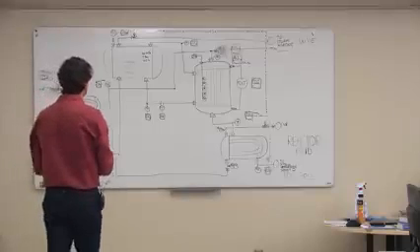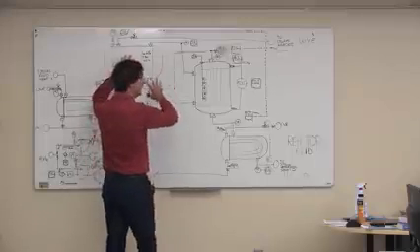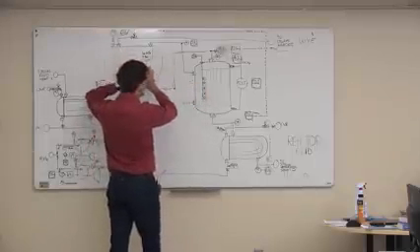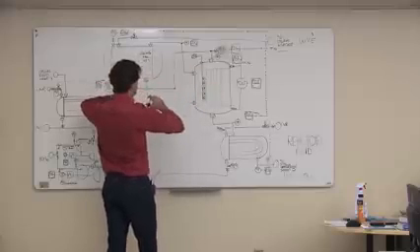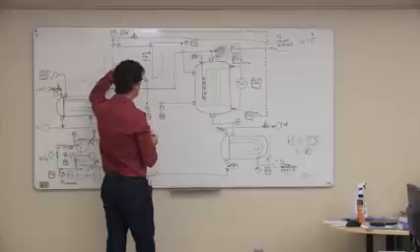Okay, so now the whole issue here is if we lose water into the reactor, it could be a very costly mistake. So we want to make sure that we always have water going into the reactor. And for the water to flow through that reactor properly, we've got to hold the liquid level at a fairly constant level.